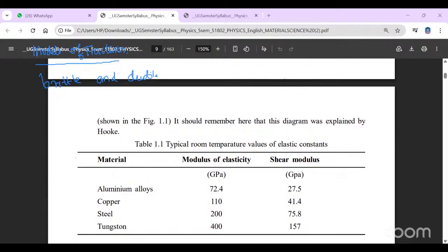Avoid sharp corners to eliminate the stress concentration. This can be done at the design stage itself. We have to avoid impurities in the base metal because they may introduce some brittle phases. One more thing is that the stress applied direction should be parallel to the elongation. Another one is that by proper distribution of atoms at grain boundaries, one can avoid the brittle phase at grain boundaries. Moreover, fine grained materials offer good protection against brittle fracture.